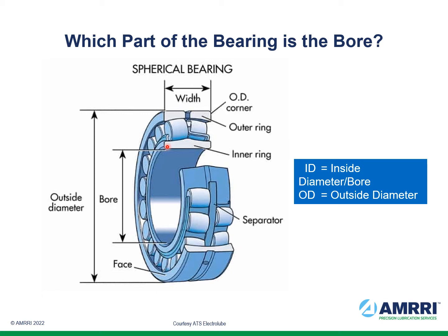The axial face plane from one side to the other side of the bearing is referred to as the width. All these dimensions are generally considered in millimeters, and they all come to play in determining which product is going to be used. The remaining variable, which is a very, very important variable, of course, is the speed with which the shaft is turning. The speed is referred to with a small n value in almost all of our machine maintenance reliability calculations.